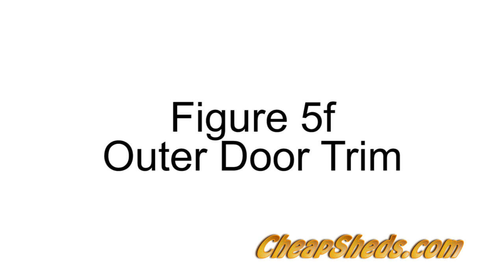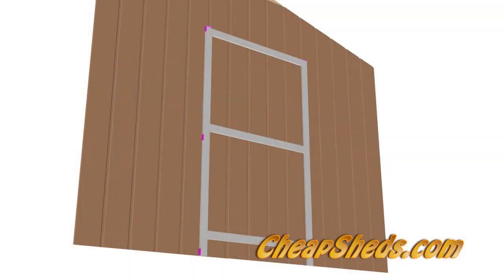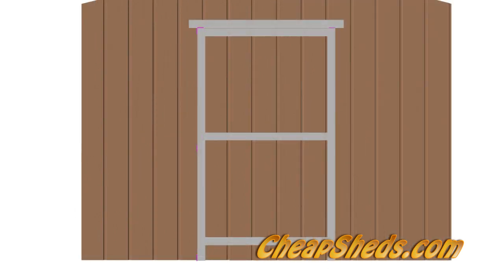See Figure 5F outer door trim. Cut 5 spacers from scrap trim about 1 inch wide. Lay 2 of these spacers along the top trim piece and the other 3 on the outside of the first vertical piece of trim. Lay a piece of trim horizontal along the top 2 spacers and another piece vertical along the other 3 spacers and pull them tight into the spacers.